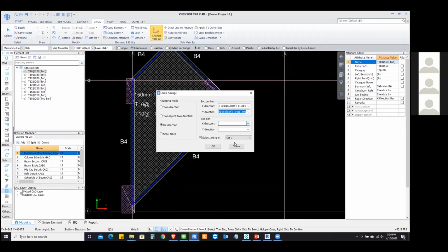And then it's asking me, okay, do you want to place it along the axis grid, which is this way, or do you want to place it something else? So if I just skip this part, I'll actually be able to pick, let's say, parallel to something or 2 points. I pick up 2 points and it will arrange in that particular direction. But direction swap and all of that stuff are another topic. Let's just proceed with OK.